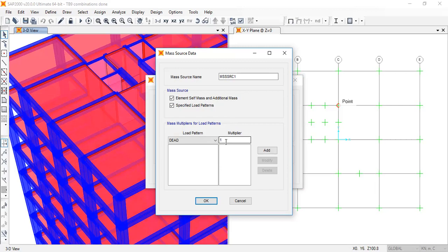And also the loads from the additional finishes, I didn't take it. Sometimes some people use a line load at the perimeter, right? Uniform line load, UDL at the perimeter to account for finishes, but I still didn't use it. So I will assume dead load was also there.